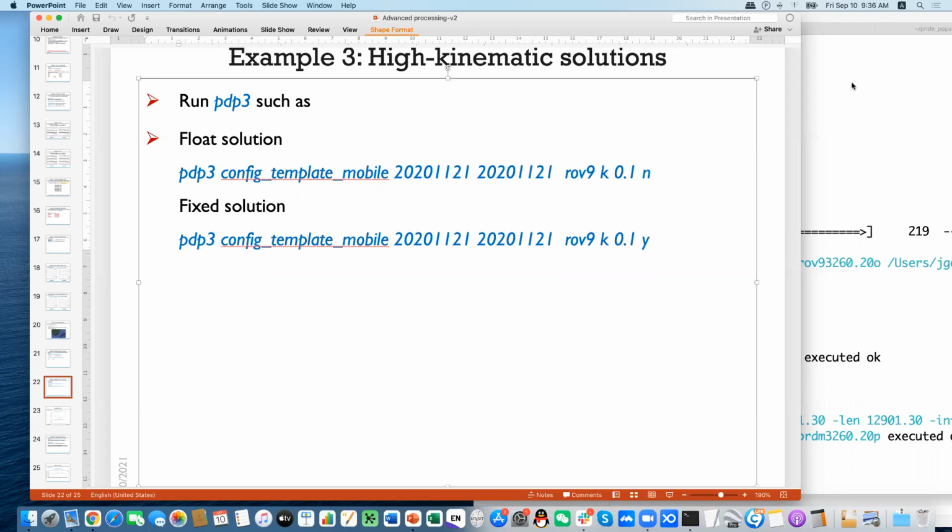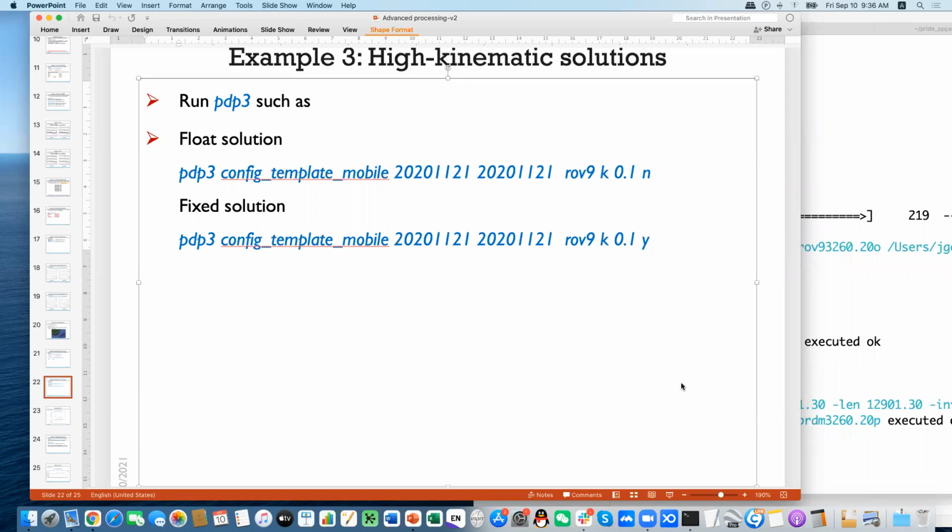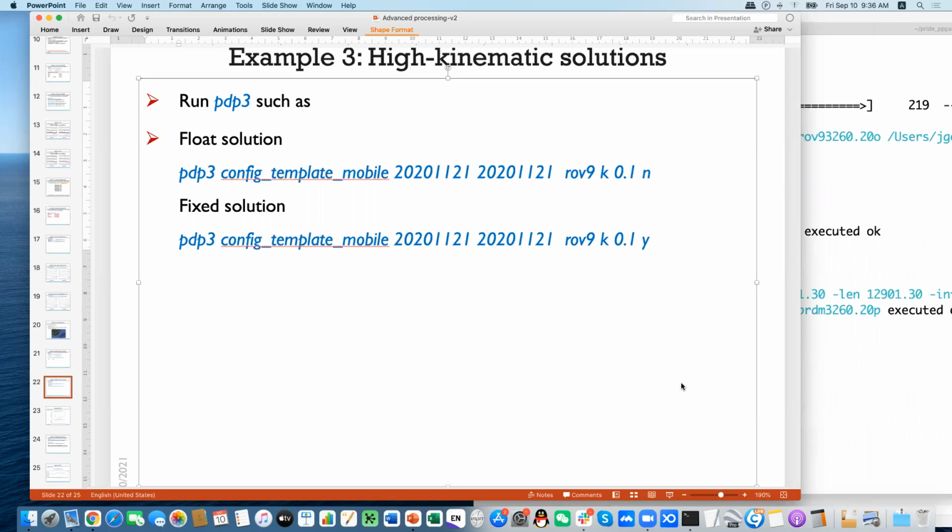Let's see what the question is. Would it be appropriate to apply the polar tidal correction to ship GPS data? Yes, I think so. Polar tidal corrections for shipborne GPS data are fine. The polar tidal correction is quite small compared to solid Earth tides and ocean tidal loading, so it has minor impact, but you can use it for shipborne data. That will make sense to do.